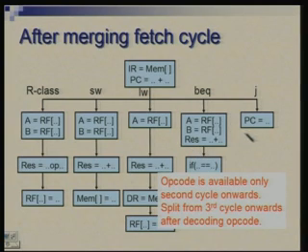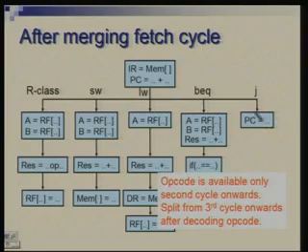The only trouble comes with jump here, because jump requires that we transfer a new value to the PC, but that we cannot do for all the instructions. That would mean that after every instruction a jump will be carried out. So therefore, we need to postpone this to the third cycle.